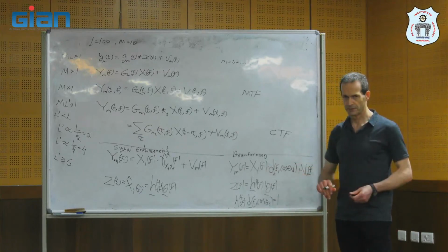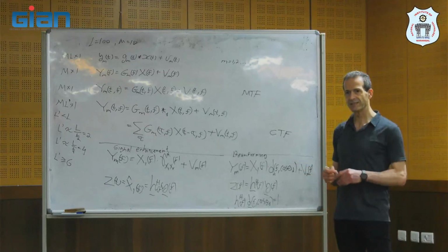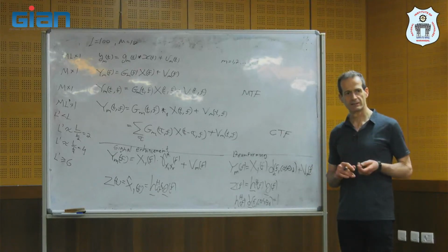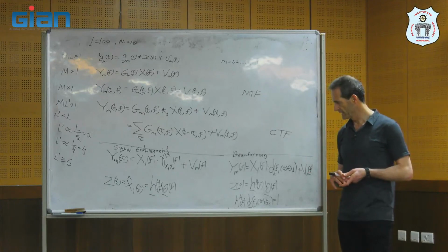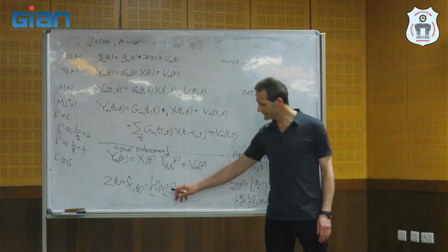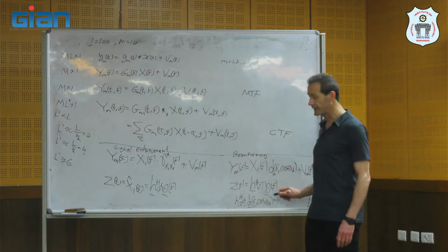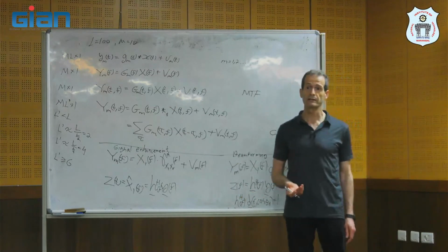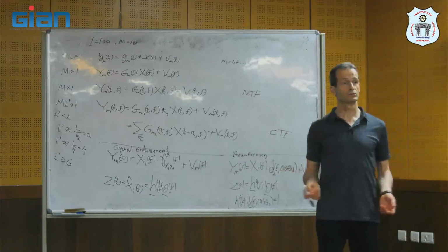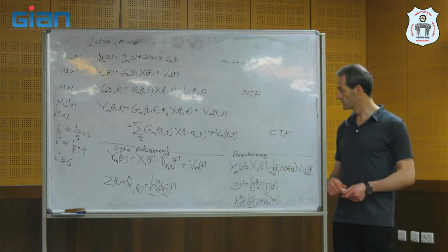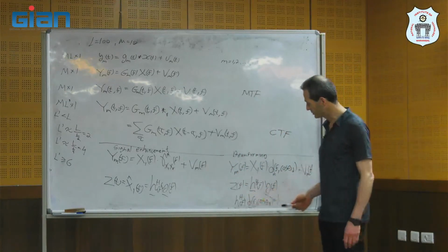This is beamforming. But you see, it's very similar, so the methods also are similar. Here, we don't necessarily use this constraint unless we want to work with MVDR or LCMV, with distortionless responses. So we add something similar to that.